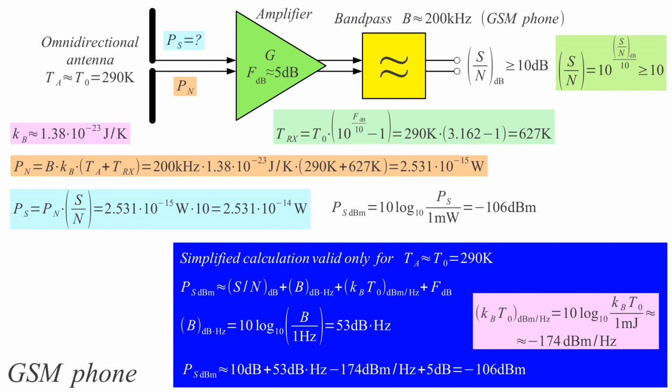Still, 10 to the minus 14 watts does not tell much. But if we convert this into dBm, decibels relative to 1 milliwatt of power, which is a very common unit in radio communication and also in optical communication. dBW would be the correct unit, but dBm is very popular among engineers.